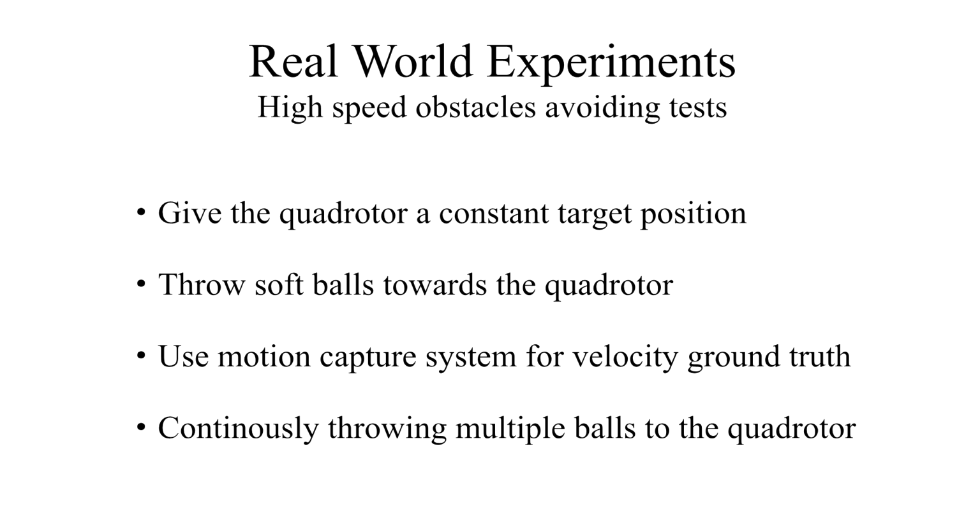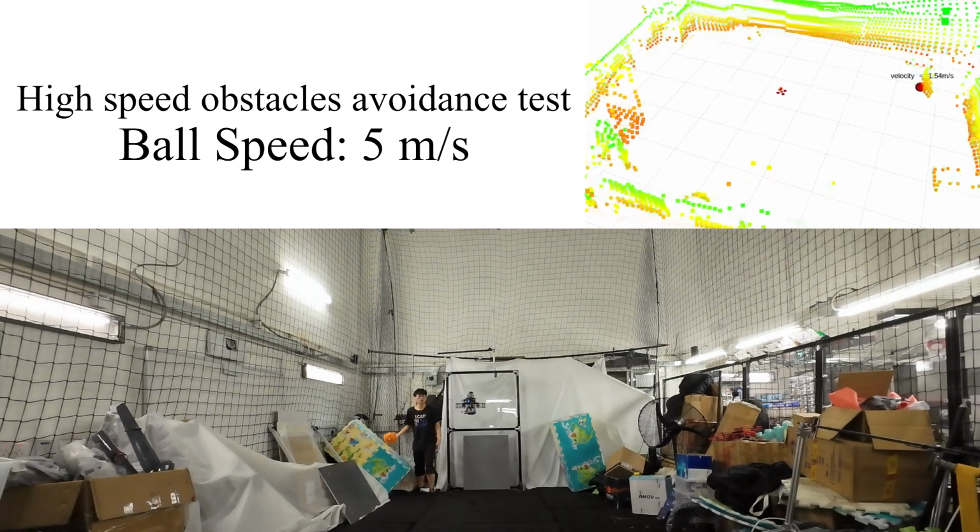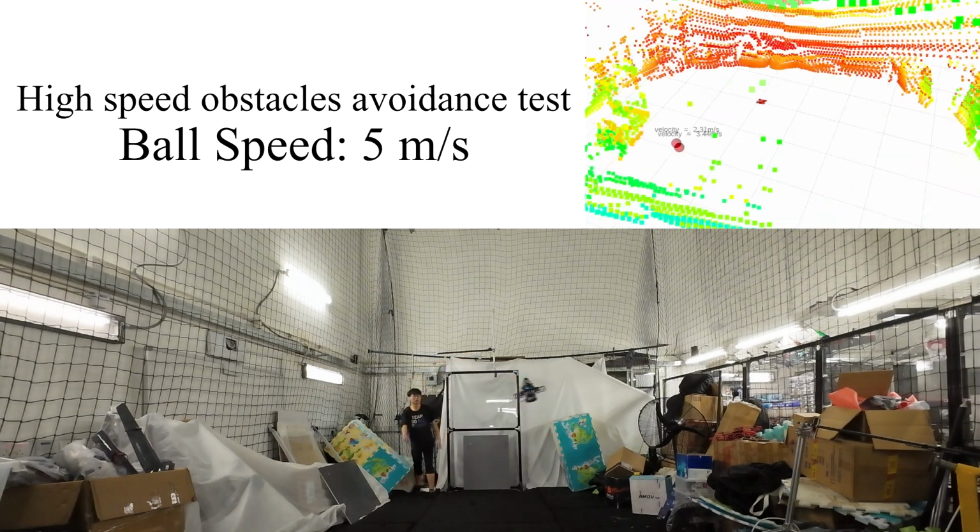We give the quadrotor a constant target position and let it hover, then throw soft balls towards it. We use a motion capture system to record the velocity of the balls and the motion of the quadrotor. We also test the quadrotor's performance while continuously avoiding multiple high-speed obstacles. In this experiment, the quadrotor was able to avoid dynamic obstacles flying at speeds up to 6 meters per second.